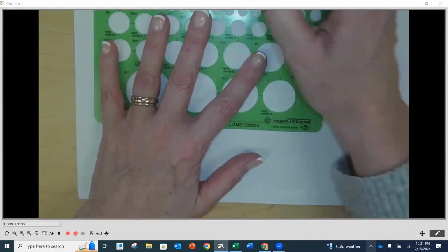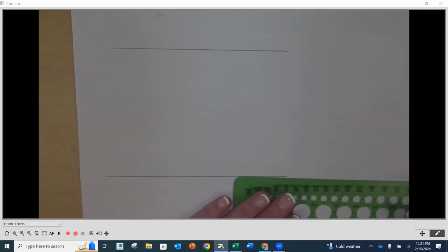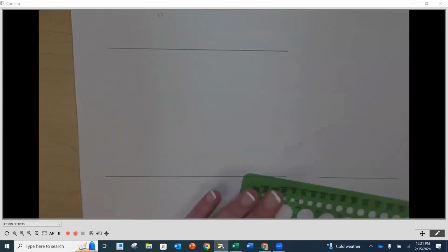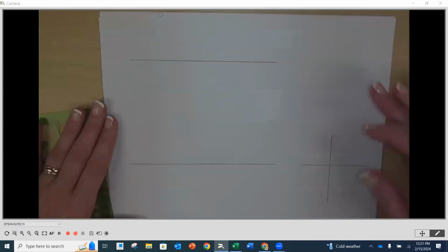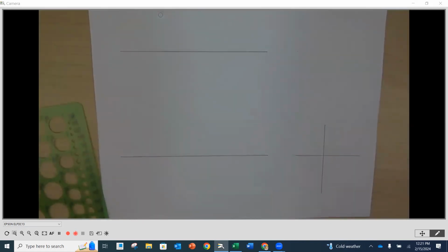Up here, I'm going to put my top view. These are going to be an orthographic projection, so make sure that you're drawing them as such. Don't do what the book does. I think it's very confusing. We're doing an orthographic projection so that you can see how things line up. This is a skill that is required out in industry. A lot of people are going to be sketching and drawing things in front, top, and right side views, and you're going to have to be able to interpret what's going on. Pictorials are nice, but they're not always going to be available. When somebody's trying to get their ideas across, usually this is how they do it.